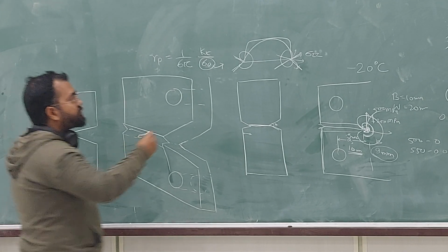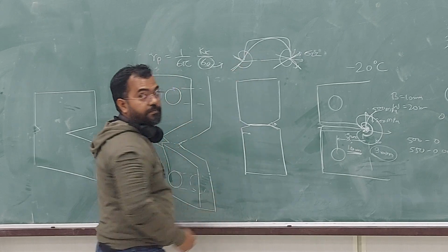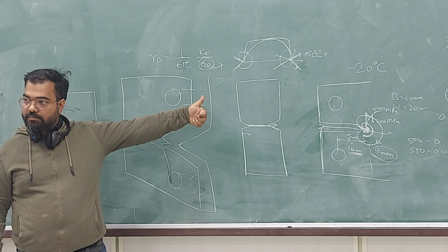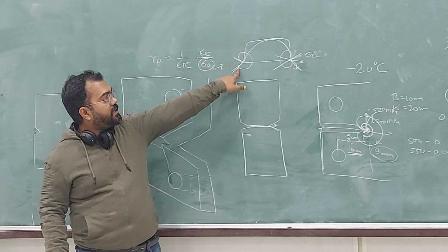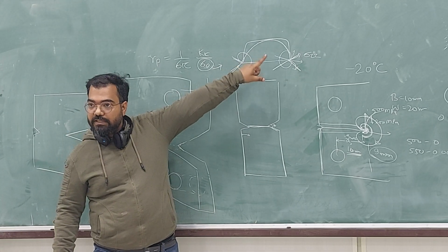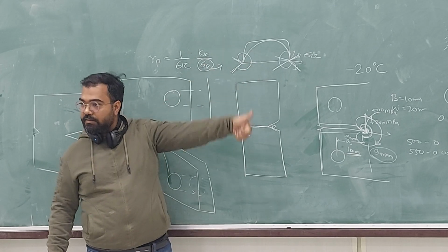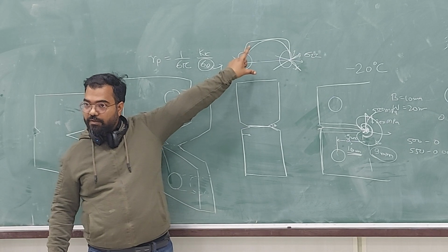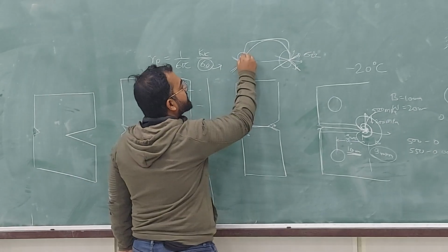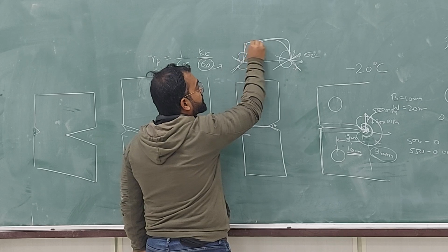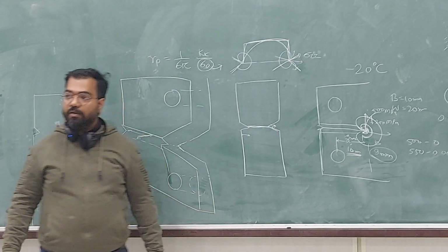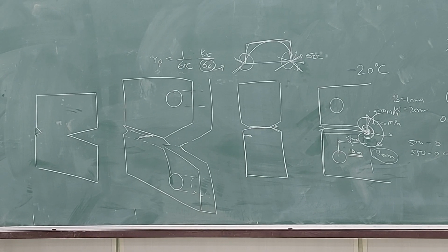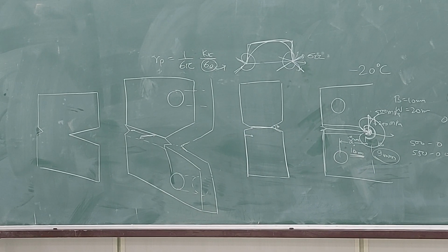The stress which was going down, sigma zz, is sigma yy for the side grooves. For this crack, the stress in the thickness direction is actually the stress perpendicular to the crack. So that is going to increase because of this crack. And then the stress profile will change, probably to this, and then you will have plane strain all around. Okay? So that's another reason why you do side grooving.